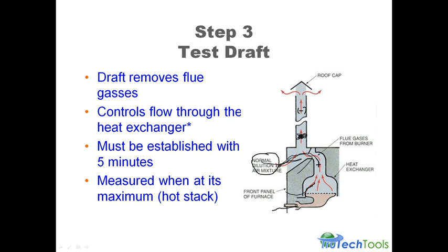Now the issue becomes if enough of that flue gas keeps recirculating in the house, eventually you're going to displace the oxygen and you're going to start to make CO. So we don't want this to happen for long periods of time. But if you had a bird fly down your chimney in the middle of the night and your flue gas spilled overnight, odds are you're going to be a heck of a lot safer with a little flue gas spilling in your house than you are with your house catching on fire. And that's the way the appliances were engineered. So the draft hood is engineered for safety. And today, we don't have draft hoods, so we have rollout switches. So now if the flame comes out backwards, it impinges on a rollout switch and shuts the burner off.